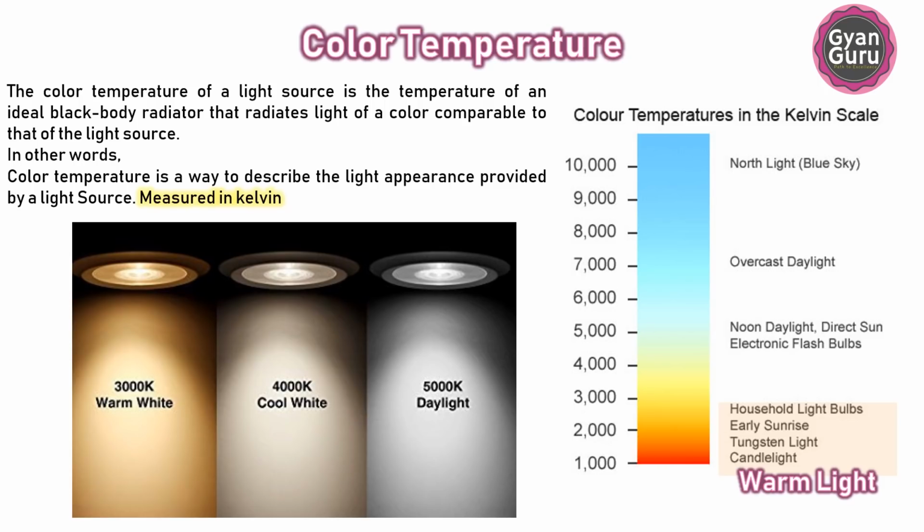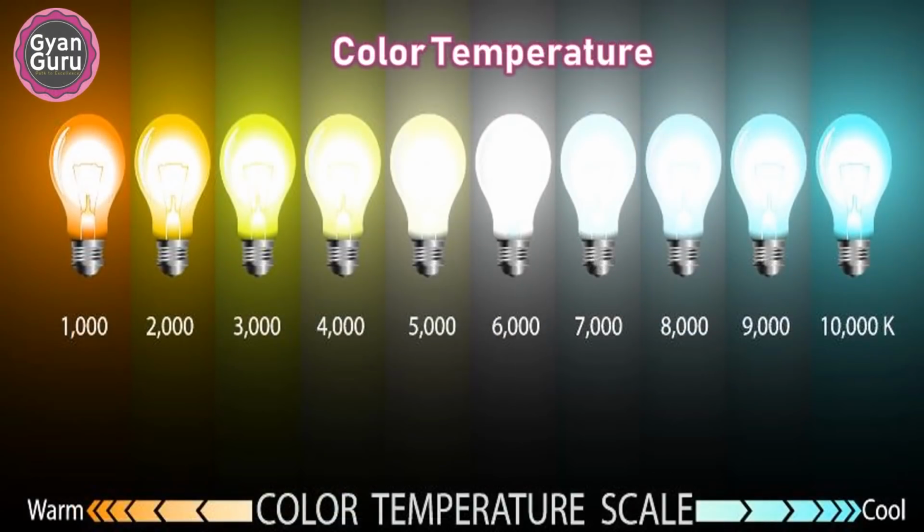Color temperatures between 3100 Kelvin and 4500 Kelvin are referred to as cool white or bright white. Light bulbs within this range will emit a more neutral white light and may even have a slightly blue tint. Above 4500 Kelvin brings us into the daylight color temperature of light. Light bulbs with color temperatures of 4500 Kelvin and above will give off a blue-white light that's somewhat similar to the daylight. It is important to know what color temperature you are looking for. The color temperature of a light bulb or an LED fixture describes how the light appears when we look directly at the fixture. Nowadays, the LED bulb is dominant.